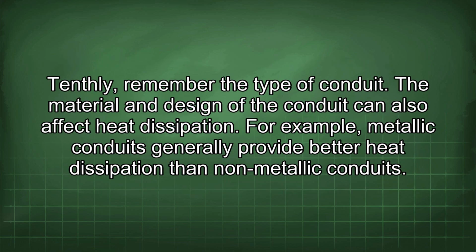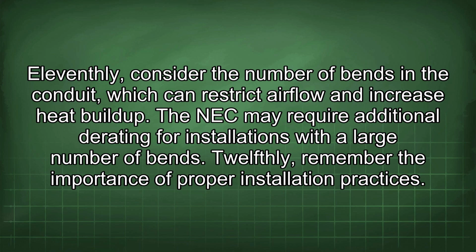10thly, remember the type of conduit. The material and design of the conduit can also affect heat dissipation. For example, metallic conduits generally provide better heat dissipation than non-metallic conduits. 11thly, consider the number of bends in the conduit, which can restrict airflow and increase heat buildup. The NEC may require additional derating for installations with a large number of bends.